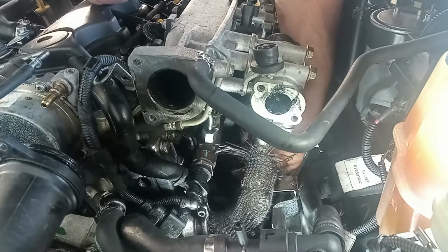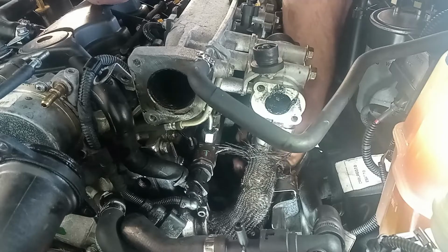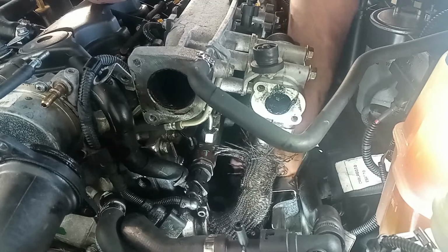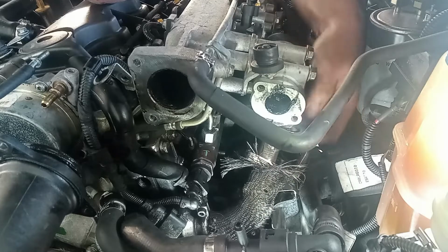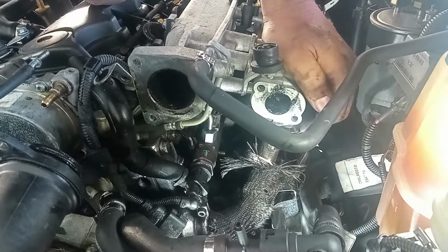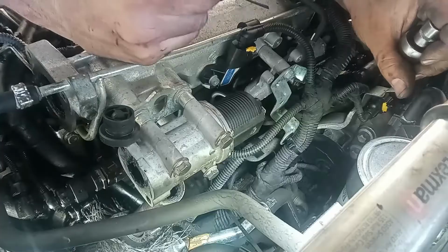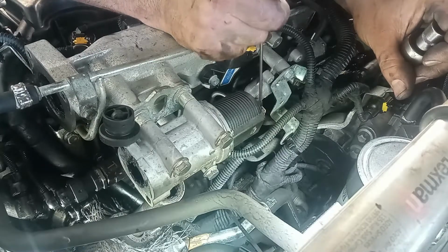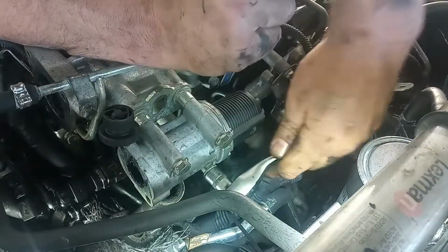If the last guy remembered to put it, unlike the other EGR that I did on a 147, where it was not present. A pipe snapping like that means that it was forced in place. This is terrible, guys. This is terrible. Gasket, now very straightforward. Take out the connector here, already kind of broken. 3 bolts over here, 13mm head.